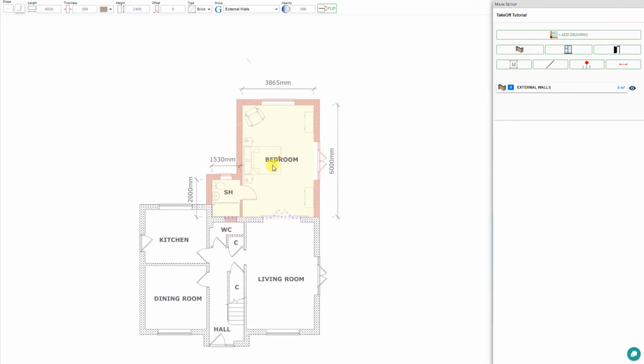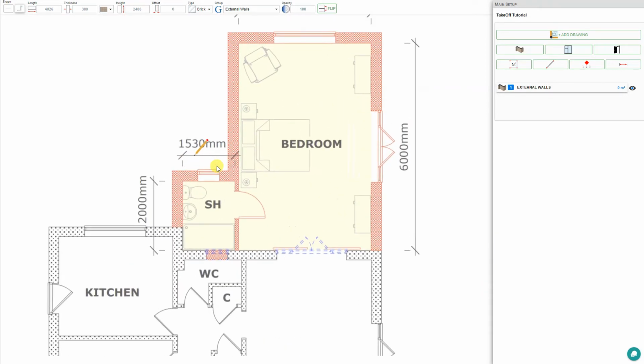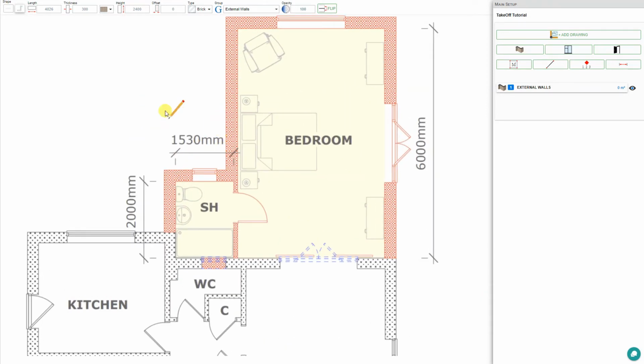Now let's position our floor plan centered, zoom in nice and tight, and now with our cursor, which is activated with the wall tool as a pencil, we can pinpoint our pencil to the outside corner of the wall and click on the outside corner. And then move our mouse to the next corner. And because this is freeform, we're not certain that this is going to be exactly straight. So we'll hold our Shift button down, and now our wall snaps automatically to the right angle. So now we can click on the next corner of the wall here, and then continue moving along.